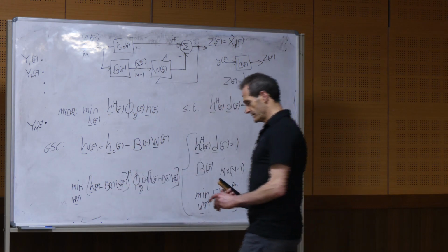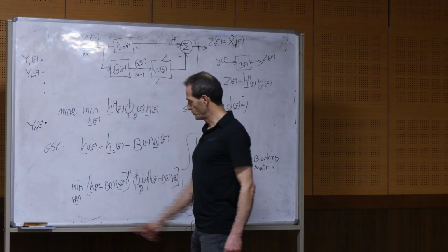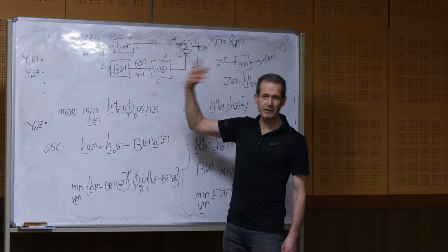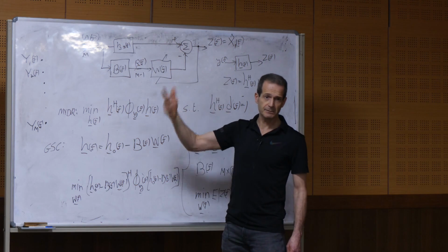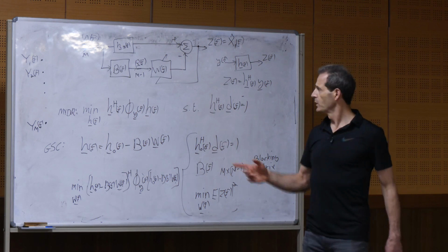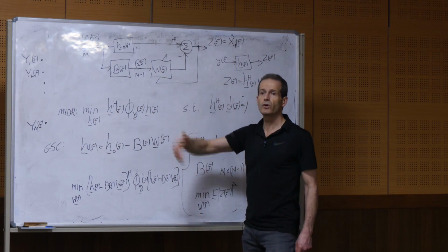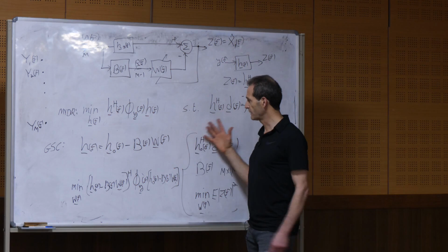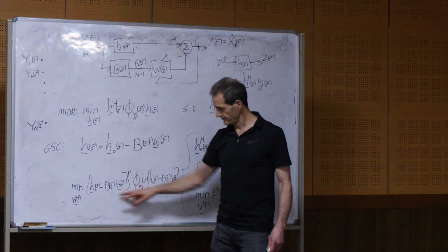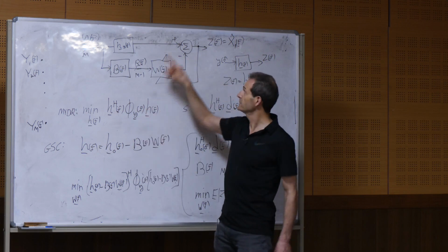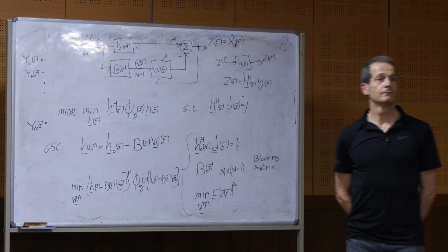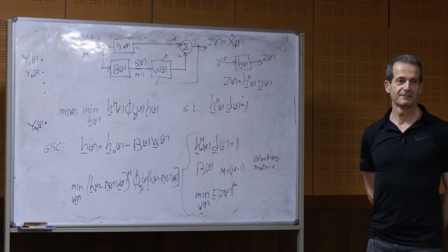Very nice. The major advantage is that to find the solution to minimum variance, we can use an adaptive filter. So all the methods for adaptive filtering, like LMS, least mean squares methods, and normalized LMS, and RLS, and all these adaptive filtering methods, we can use for W. So we can do it online, in real time. We don't need to do something offline, just like we solve here. Also this, we can solve offline using least squares, okay? But in real applications, it's better to use adaptive filtering methods, all the LMS family of solutions. Beautiful. Don't you think it's beautiful? Very beautiful work.